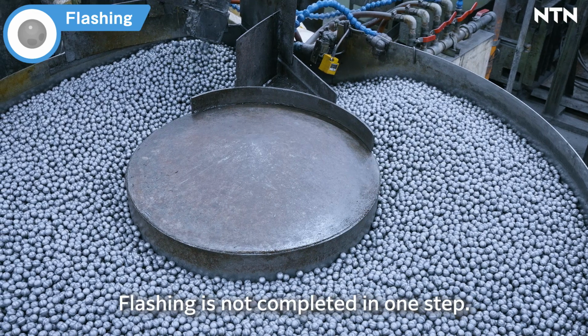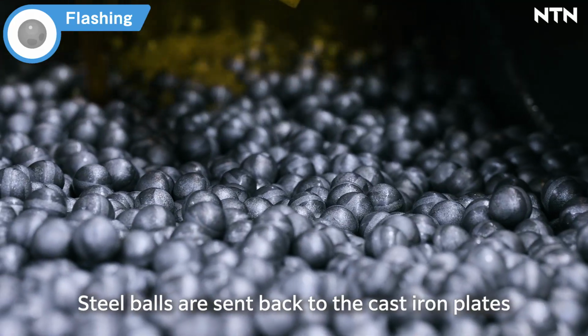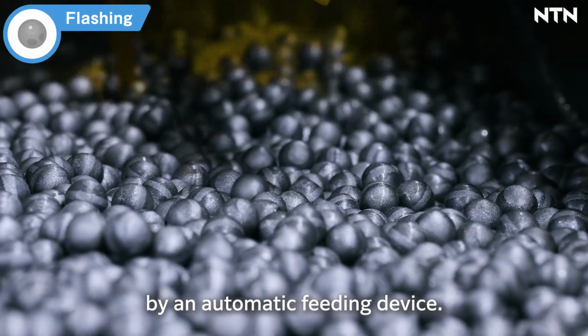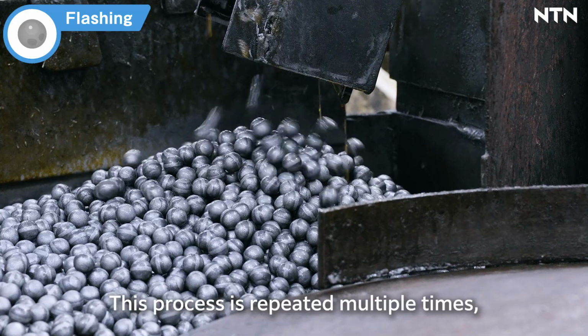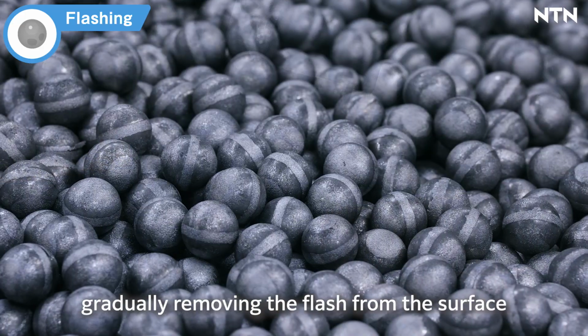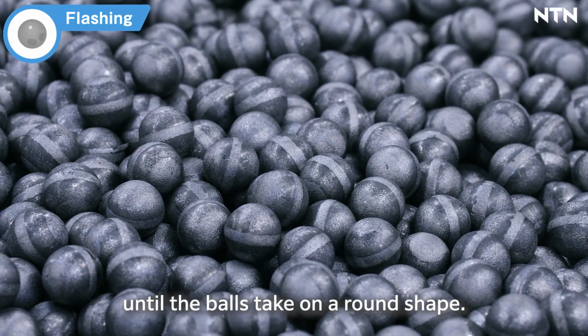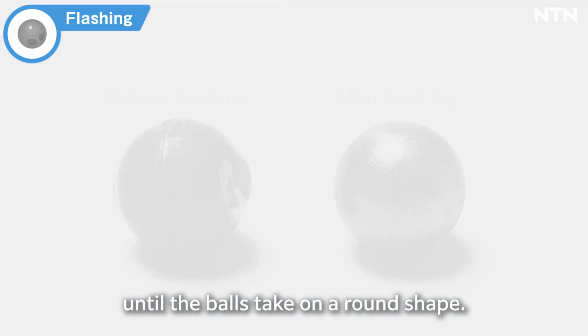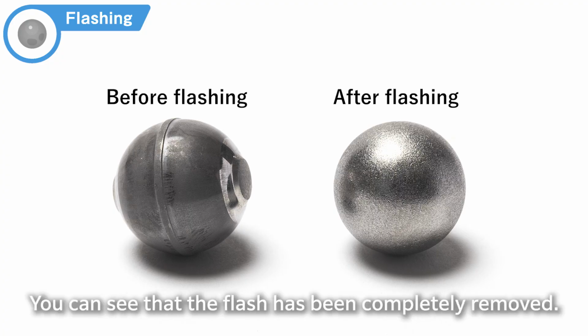Flashing is not completed in one step. Steel balls are sent back to the cast iron plates by an automatic feeding device. This process is repeated multiple times, gradually removing the flash from the surface until the balls take on a round shape. Look at this steel ball after flashing. You can see that the flash has been completely removed.